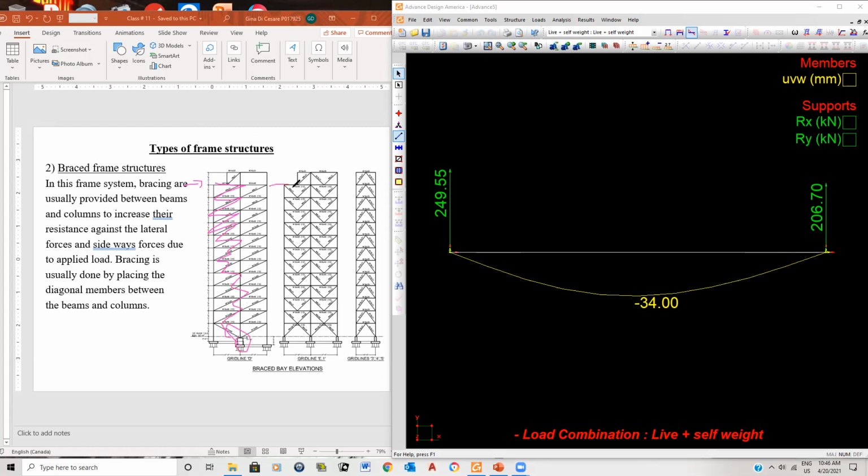Like for example, this lateral, if you notice that this is a K-truss, okay? So in other words, these things are like trusses that are put in a vertical direction. And when I put a load here and I put a load here, as the wind or the earthquake creates lateral loads, this system will allow the load to make its way down to the foundations where hopefully it has the resistance to keep everything stable. Now, of course, this thing will displace a bit, but at least it will not collapse, okay?